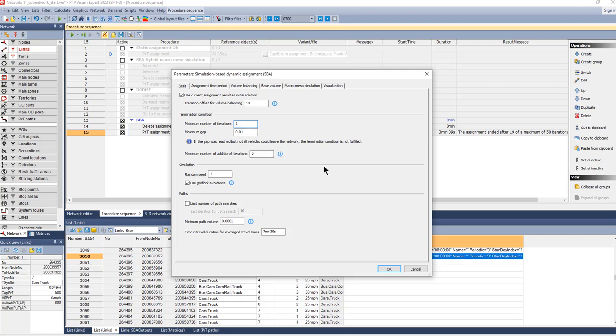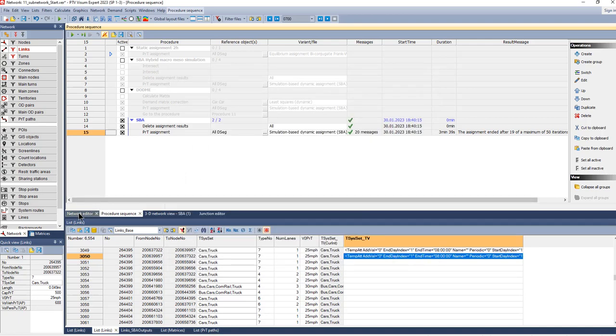That means we only do a network loading process where vehicles react to the road closure. If you model a planned event, so the drivers are informed, then you would run an SBA assignment in the normal way until an equilibrium is reached, and in that case you assume that the drivers do know about the event. So I skip that for now, but would like to